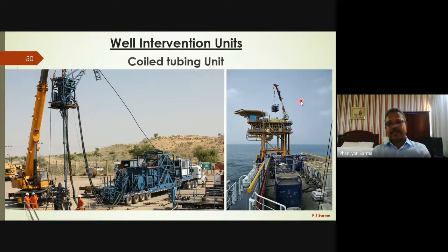It's a similar kind of injector head, because the injector head always has to be installed on the wellhead, and the coil tubing has to be, of course, on the platform. Or sometimes the coil tubing is also deployed from the barge itself. And if there is not much place, then all other equipment is kept in the vessel, and it is connected to the platform or the well through a Coflex hose, and the operation is done.